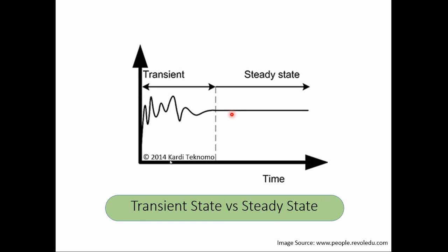This will help us to simplify our energy balance equation for open systems. In fact, it is not just mere simplification, but it is more like a practical application. For example, if you take a steam turbine, we are not quite interested in its behavior at the starting cycle as well as the shutting down cycle. What we are more interested in with the steam turbine is the period where it is providing us the electricity. So that is a steady state situation.